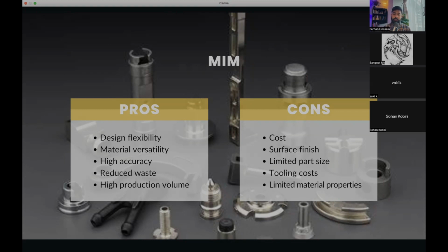It's different from casting or other things where you're pouring it into a cavity. You're literally injecting the liquid pellets, pressurized, into a cavity and core, and then that takes a shape and you do multiple of those. You see what I mean? So it's a little different than casting, but nonetheless very cool. And this is one of the more modern mass production techniques.